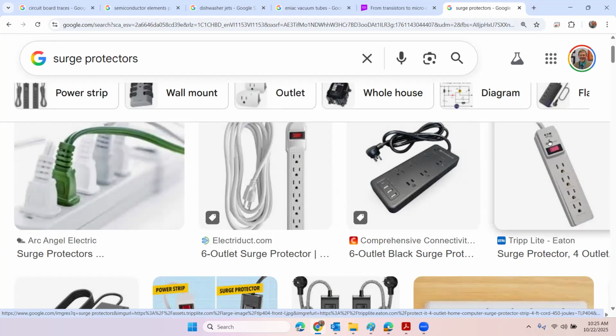If you have lower current and lower voltage, the surge protector doesn't do one thing to protect you from that problem. The surge protector only protects you from excess or surplus, like when there's a lightning strike or when the generators at WAPA kick back on and there's a sudden burst of electricity. That's what a surge protector helps you do. But there's one Achilles heel of this surge protector that's a gotcha, and I want you to remember this.